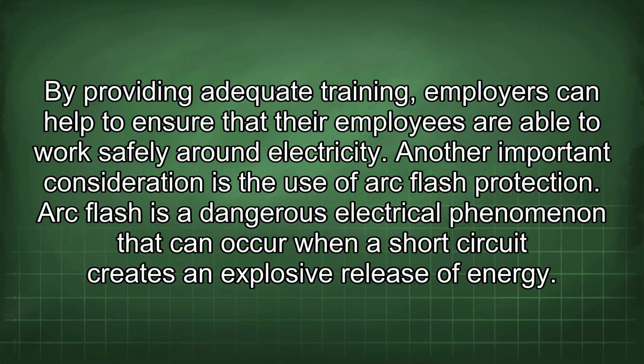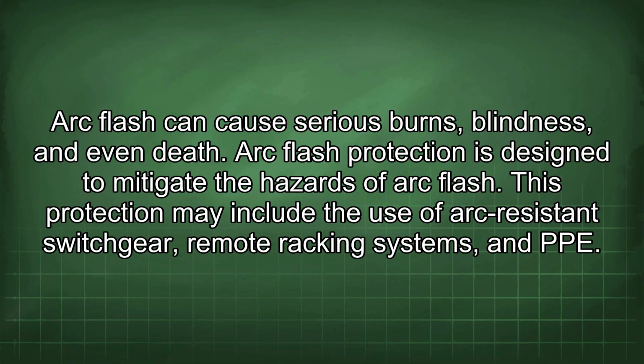Another important consideration is the use of arc flash protection. Arc flash is a dangerous electrical phenomenon that can occur when a short circuit creates an explosive release of energy. Arc flash can cause serious burns, blindness, and even death. Arc flash protection is designed to mitigate the hazards of arc flash. This protection may include the use of arc-resistant switchgear, remote racking systems, and PPE.